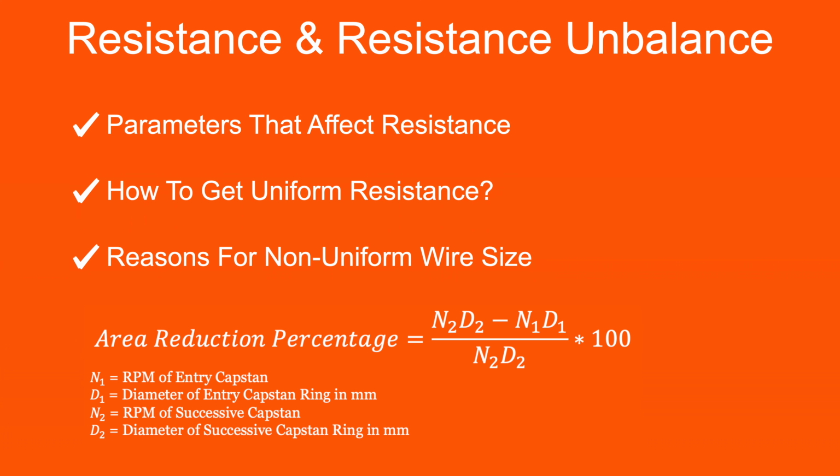Another important thing is that the wire drawing lubricant cooling system should be designed well and should not allow the lubricant temperature to go beyond 45 degrees Celsius. If the lubricant temperature goes beyond that, it loses its lubrication properties very fast, and without proper lubrication there will be metal sticking in dies, which will again cause diameter variation and surface scratches on the wire.